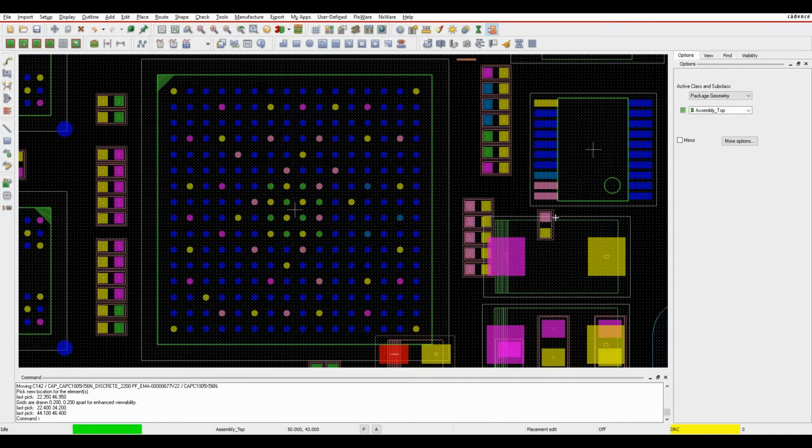Okay, this how-to video is going to talk about a new grid option that's available for all levels of the Cadence PCB tools, so OrCAD PCB Designer Standard all the way up to the Allegro PCB Designer. And it's called Relative Grid, which gives the ability, especially when placing components, to change the grid on the fly, which can be quite a useful feature.